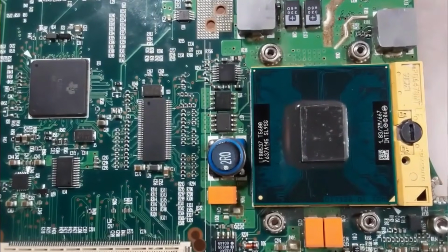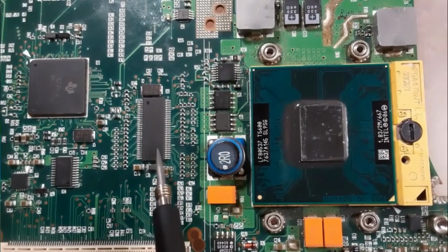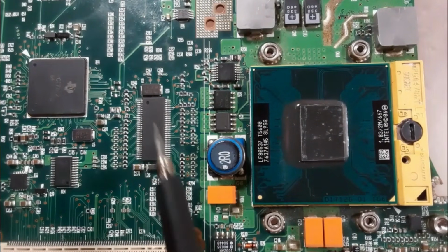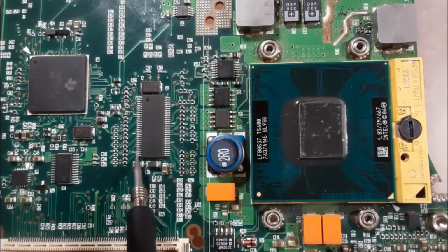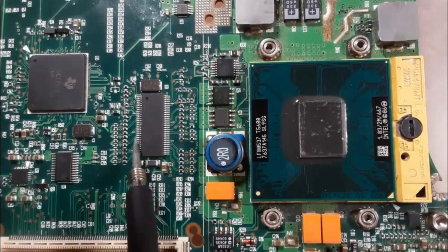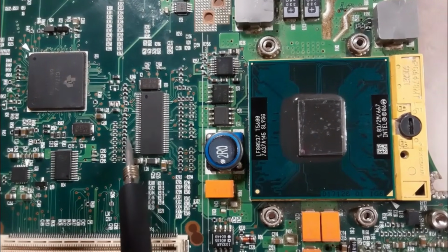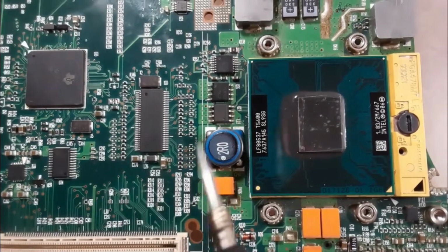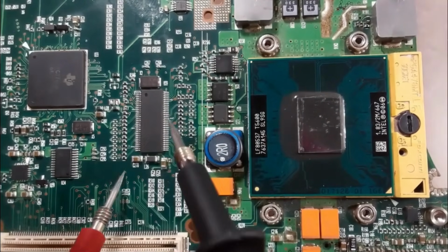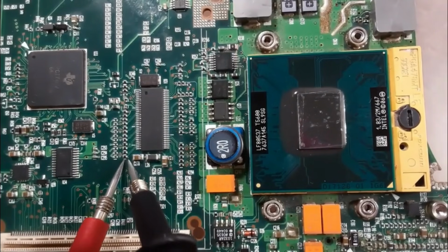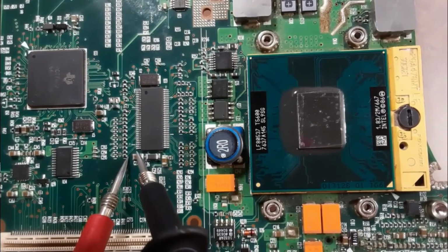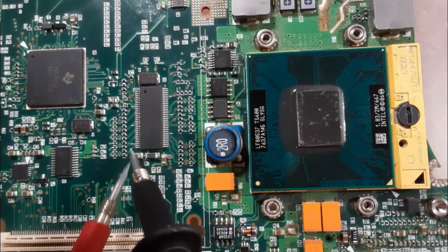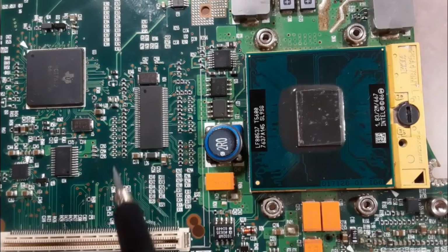So here, as you can see, we have the clock generator. Always near the clock generator we have a crystal or a quartz. As you can see, here we always have small buses. All clock generator pins are connected to other components. For example, let's check this resistor. As you can see, we have here a tin bus. So let's check this. The resistor is connected to this pin, as you can see. Why? Because I follow this bus.